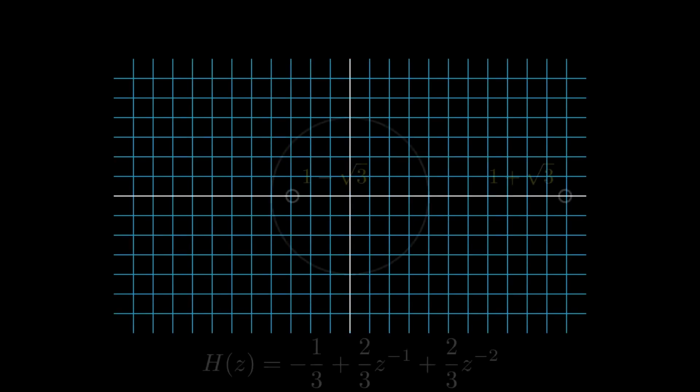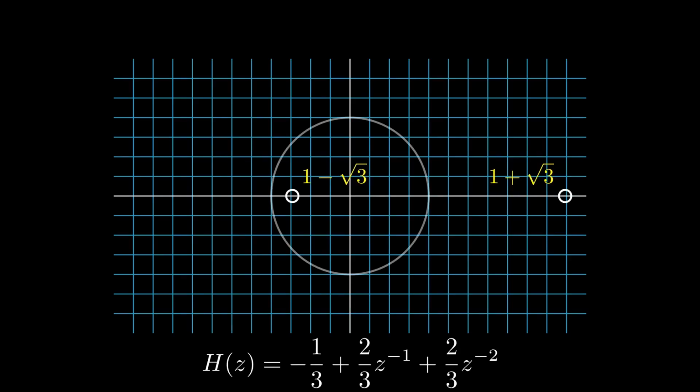Now let's plot these two Z values on the complex plane along with the unit circle that corresponds to our frequency spectrum. This is called a pole zero plot. The circles in the pole zero plot represent the Z values in the complex plane where the transfer function output is 0. We call those Z values zeros. Usually though, this plot is given without the labels on the zeros. It would also show the poles of the transfer function, but those aren't necessary for us.